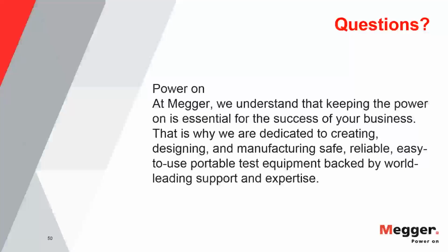So for a commissioning test, when you want to combine all of that, CR and then the DAC, the DAC is, as I said, just diagnostics, and its high test capacitance comes from the fact that you're just releasing one shot and you take your time charging the cable. It is not a continuous waveform. So sometimes on transmission cables, you charge the cable over 5 to 10 minutes, and then you release the shot. And of course, if you can take that time with a non-continuous waveform, you get a huge test capacitance out of that. Just to clarify this.